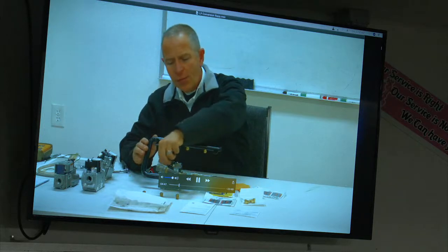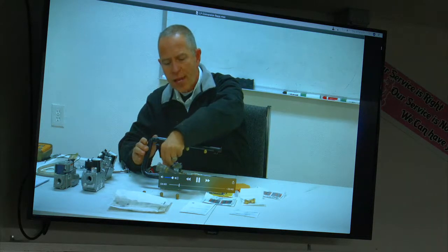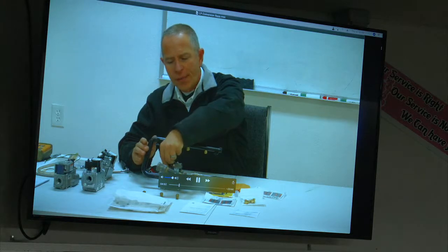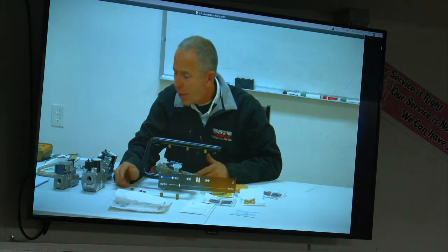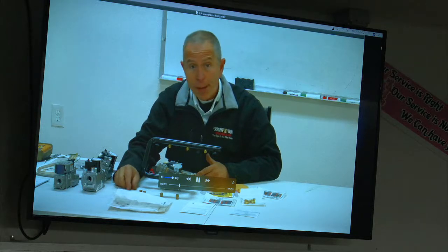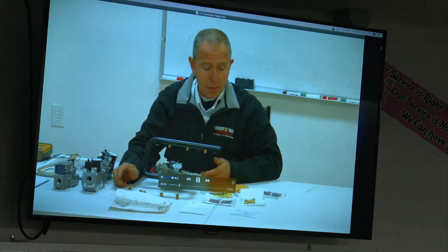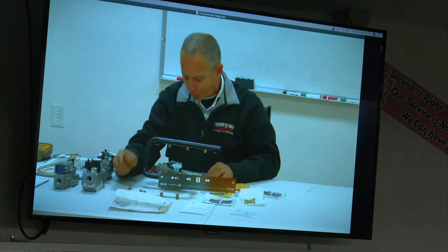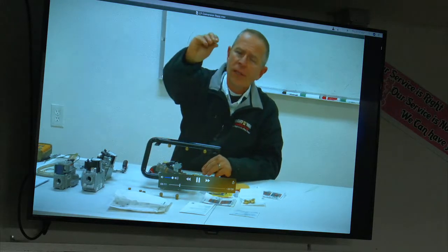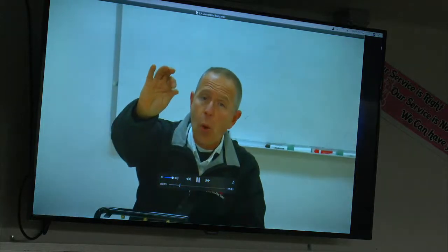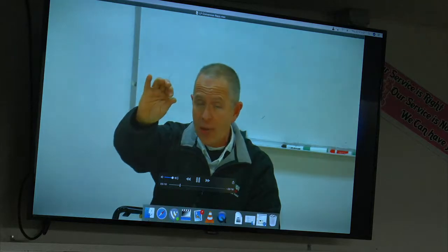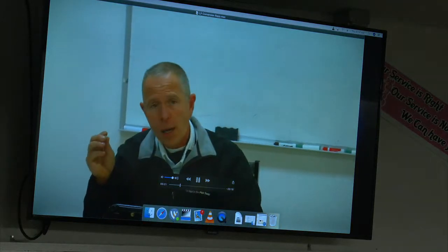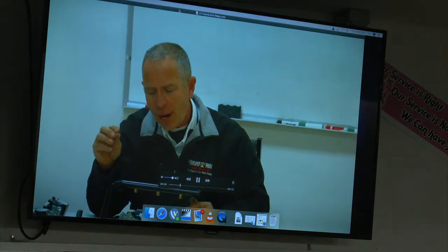So on that part there, this particular valve is a 2-stage valve. Almost all of the newer Goodmans are going to have multiple stages, 2 stages. And this one has brass caps. They could be silver, and when we convert over to propane, some of them may be black. It just depends on which type of valve you're using. Here, this is the little plastic set screw that holds the spring inside, and is where we adjust the tension to adjust the water column of this particular gas valve for a high or low.